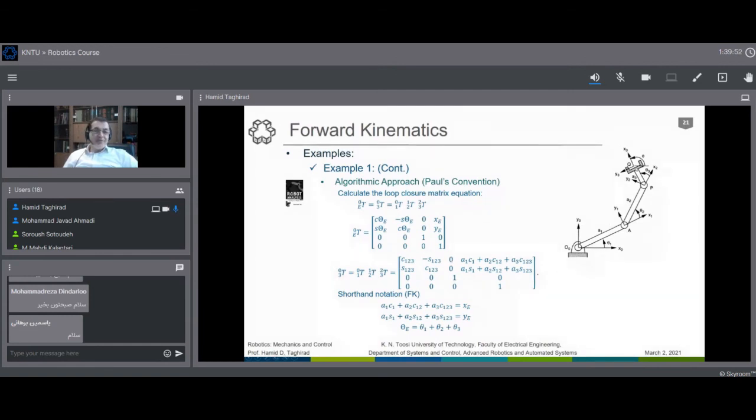You know, what we do would work with a redundant manipulator. It is very hard to say where my hand is when it is moving in space. But if I touch someplace, let's say I touched my table, you don't see the table here, but make it a fixed point. Put it here, fixed. Now move it. If we make it fixed, this fixed point can be measured quite easily. It is very hard to find it when it is in space, but when it is on the table, it is much easier. Of course, the robot should have some motion, so it should have some redundancy.